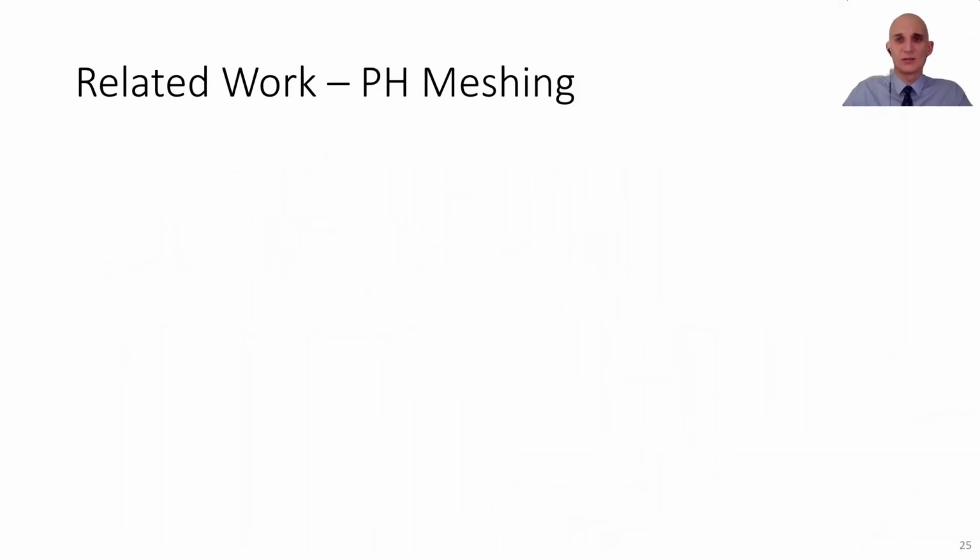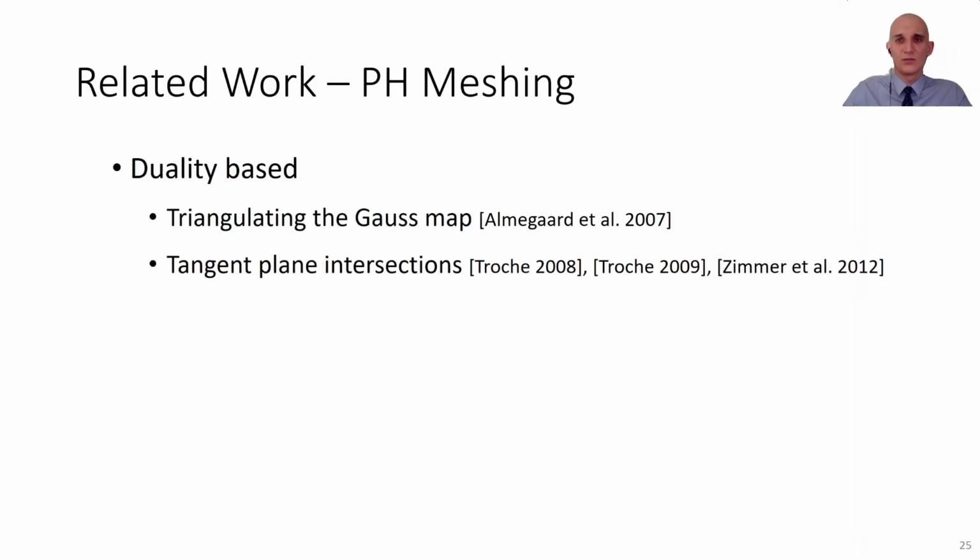There exist methods aimed at generating non-planar hexagonal meshes. Here we focus on planar hexagonal meshing. Some of the earlier methods use the duality with triangular meshes, but they often do not lead to regular planar hexagonal shapes.